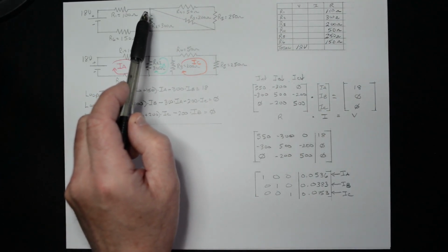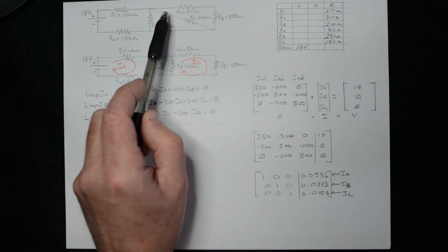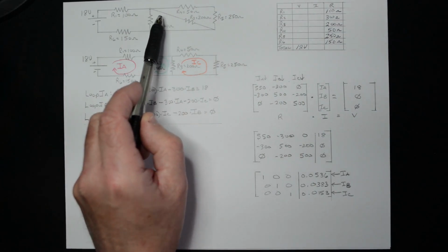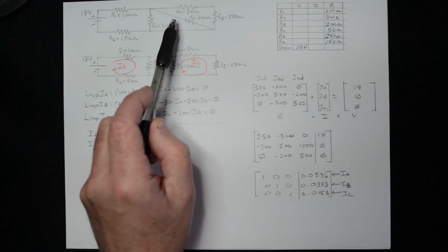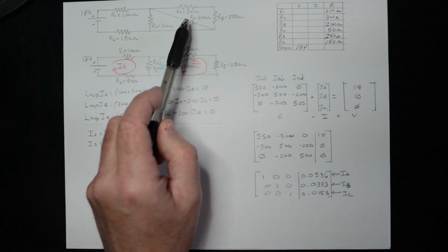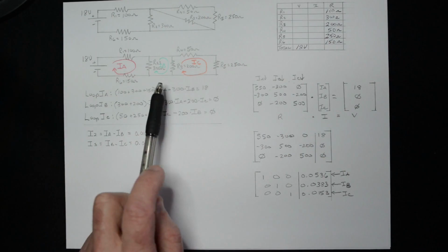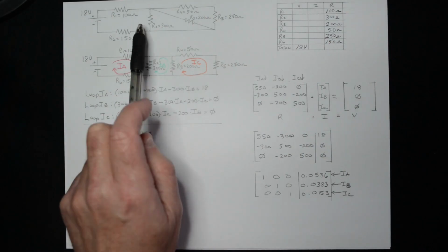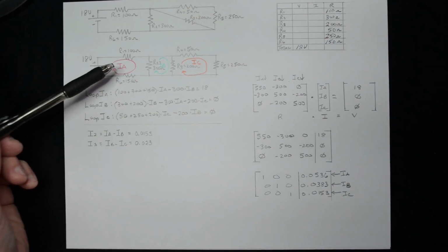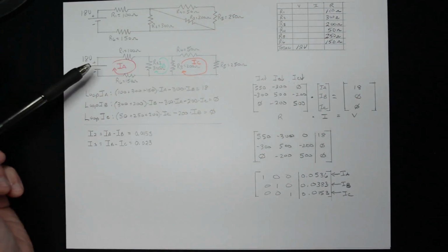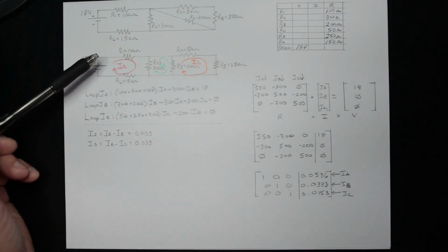So with those easy restrictions to remember, you can move this conductor here on R3 anywhere you want around here, and you can do the same thing here. And your goal is to make it parallel or perpendicular to the rest of the loads in the circuit. So you can very easily redraw this into this. All I've done is straighten up R3. And once you have it visually in this configuration, you recognize this as just something you've done 1,000 times over.